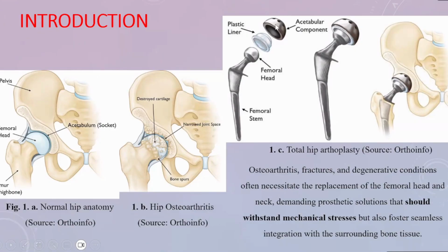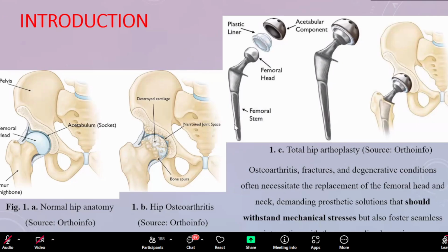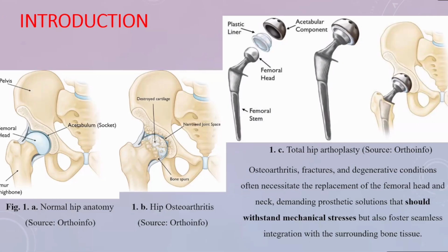There we can also use customized implants based on patient-specific geometries. The only way to make those implants affordable is through additive manufacturing, because we can't make dies and molds for them, right? With additive manufacturing, there is a possibility of weight reduction or better osseointegration, by implementing lattice structures.